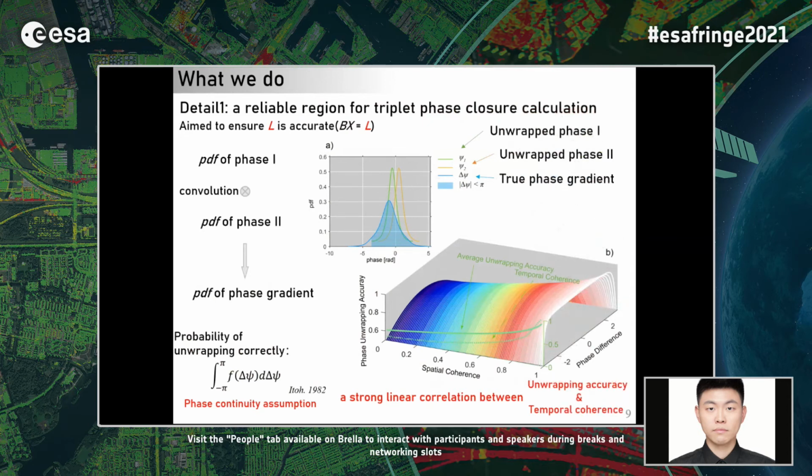In the correction method, we should concentrate on two details. Before we solve this linear equation, we must ensure L, the observation vector, is accurate. Like the displacement inversion, we need to choose a reference without displacement. Phase unwrapping error correction needs to choose a reliable region, but this region should contain at least, or nearly, zero phase unwrapping errors.